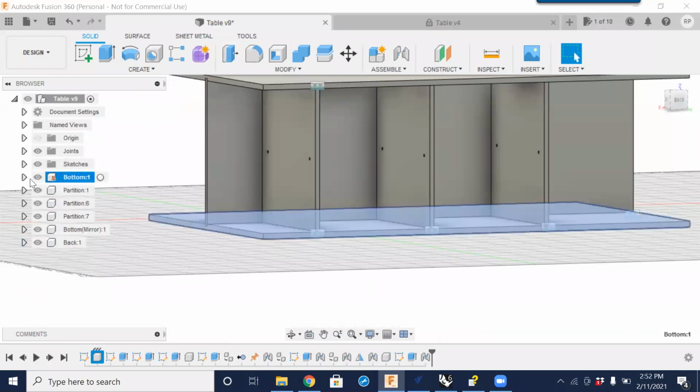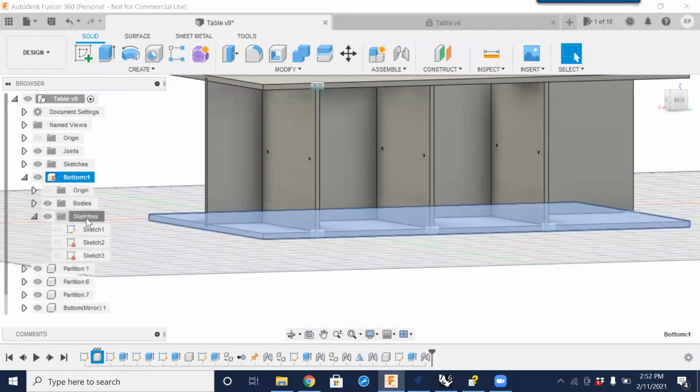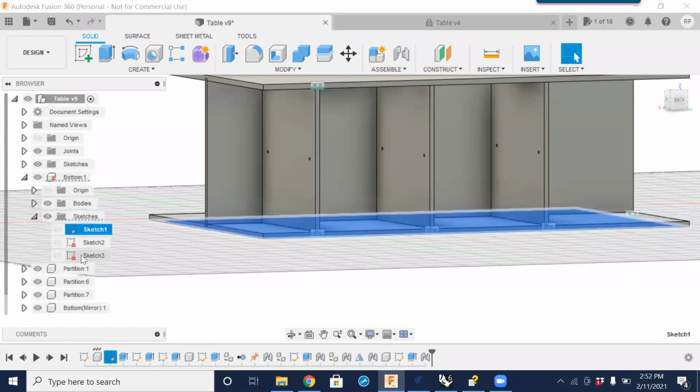I'm going to right click or open up the tree, and in the sketching, we could see, I want to get back to the extruding section of this. So to get back there, notice across the bottom of the screen, this is the timeline that we have created everything.